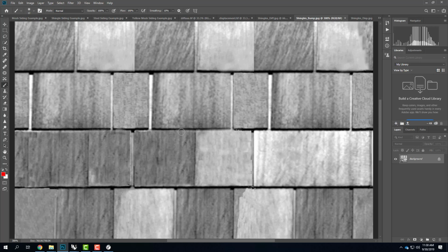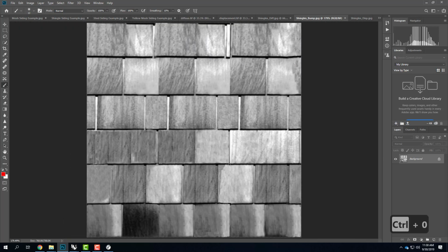So if we looked at it in cross-section, we'd start at the lowest level black, and as we came up into anything lighter than that, it would stick up just a little bit in the texture. It's not a lot. It's just a little bit of fine-grained texture. So we create that using this simple black and white image. It needs to be high contrast, so you need to have a very strong white and a very strong black in the image. And then the grays that fall in between give us that little bit of texture.